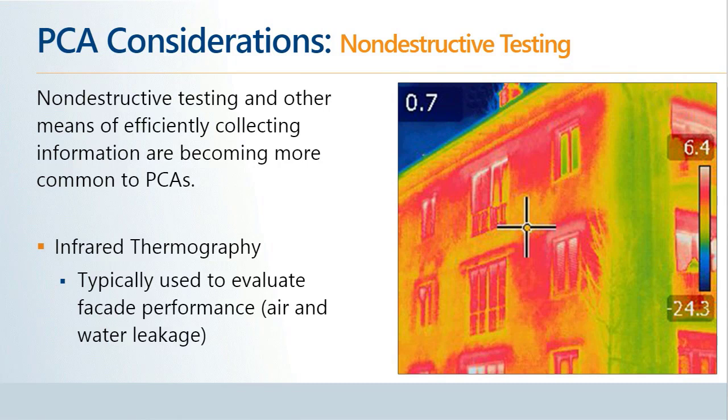We do not recommend relying exclusively on these results, but these may be effective in justifying additional work. The data captured can provide a lot of information and detail with minimal cost, and these infrared thermographies are typically performed by a trained person and will often require inspection openings to corroborate the results that were determined.